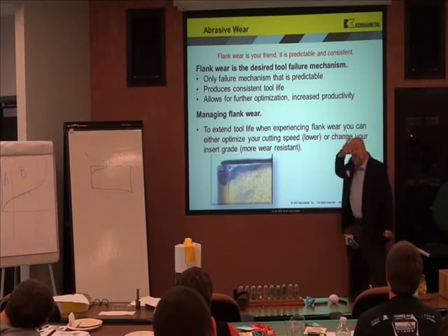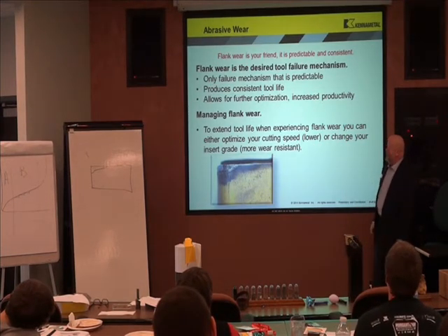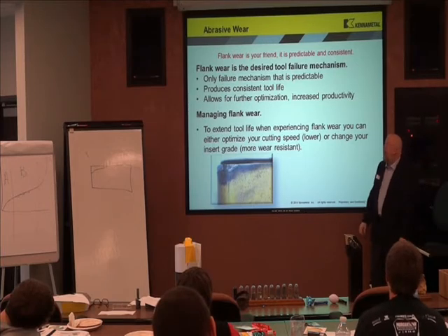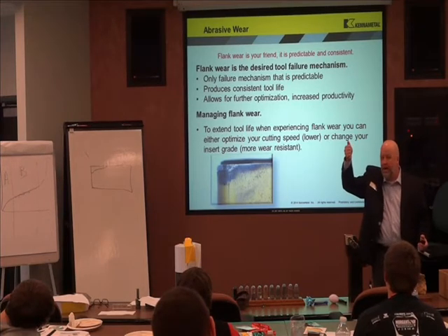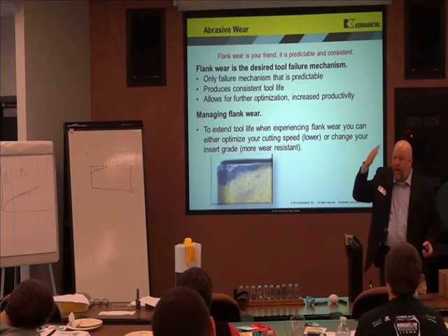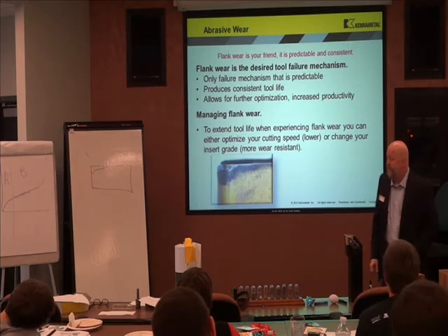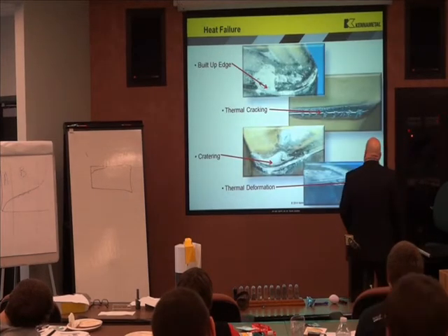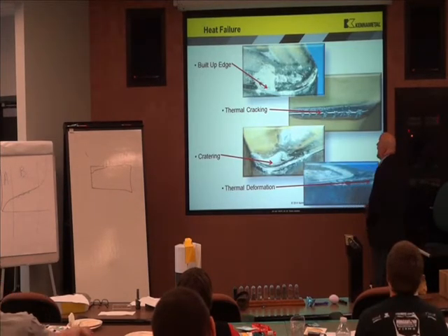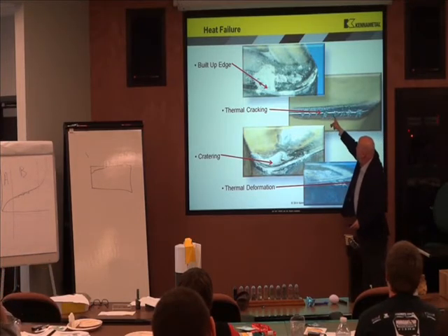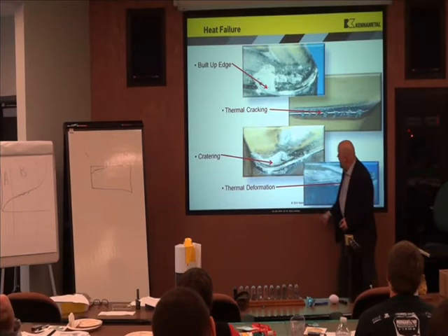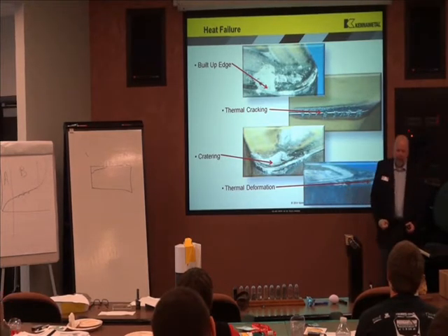It produces consistent tool life. It allows me to optimize my operation. I can extend it by playing with my speed or getting a harder grade of carbide. Harder, more like glass, takes more heat. Now, let's take a look at heat failure. I got something called built-up edge, I got thermal cracking, I got cratering, and I got my favorite, thermal deformation.